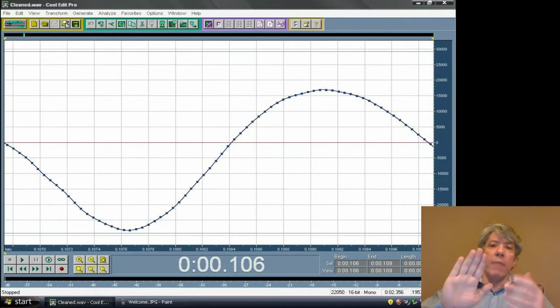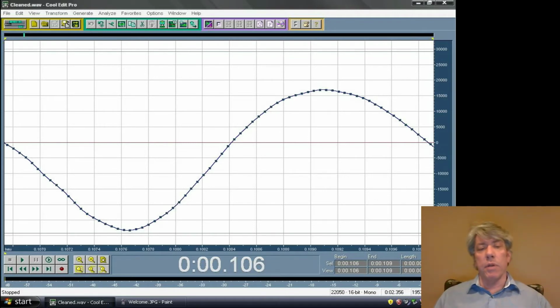You see, the diaphragm in the microphone is actually moving back and forward continuously, making a continuous analog voltage signal. But that voltage signal, by the time it gets to my computer, is being sampled at unique points in time. In other words, the voltage is being measured at unique points in time, not continuously. Not only that, but the position of the microphone diaphragm, in other words, the voltage, is not measured exactly. It's rounded off to some extent.